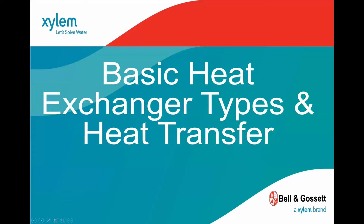Low heat transfer rate is one of the disadvantages. You think of that as just in terms of the amount of surface area when you compare it to other designs. And the limitation, we're going to get into temperature approach and temperature cross. So this says here a 10-degree minimum is what they would like to see, but I'll actually come back to that after the slide.